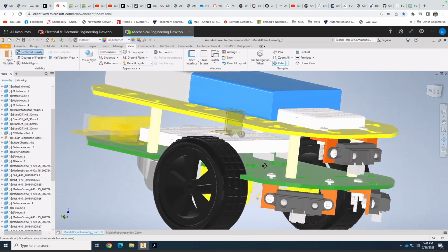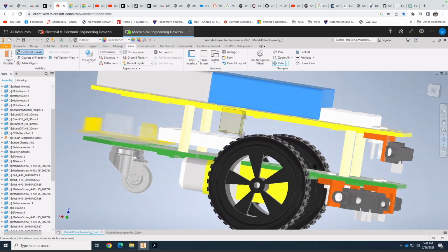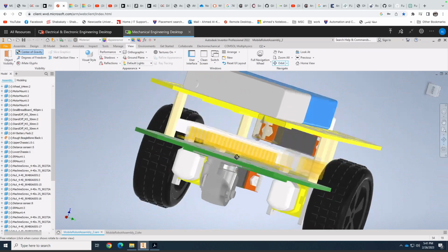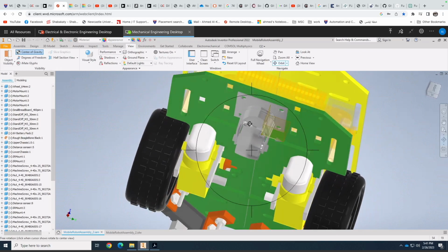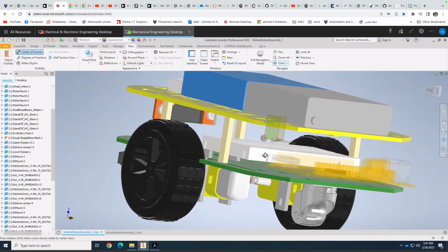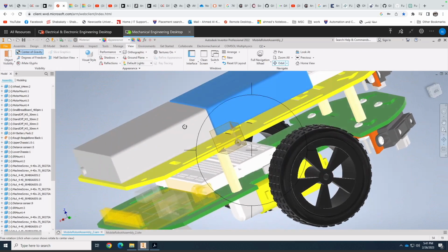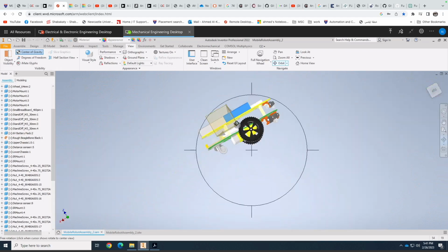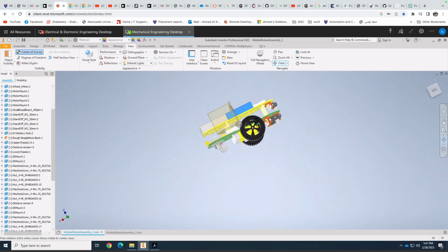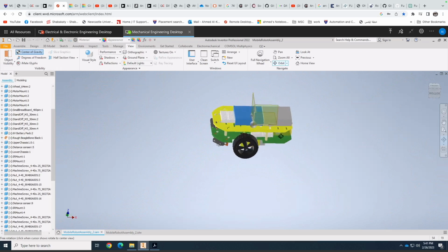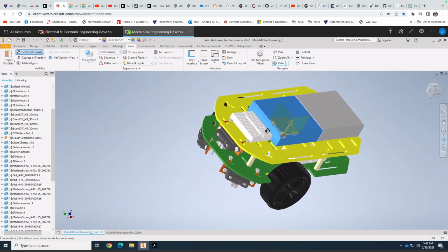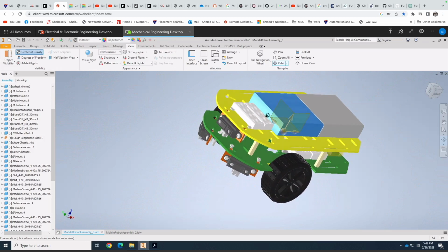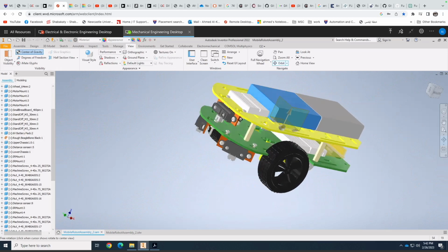The lower chassis has a board for connection of the Arduino Uno at the end, and the bottom chassis connects 2 DC motors to it, and the caster wheel is shown here, and at the upper chassis are the battery and the other chassis for the force sensor. And you can see the center of gravity is at the center of the robot, so it's very stable. And at the front of the mobile robot there is a board for connection of the battery and also the force sensor.